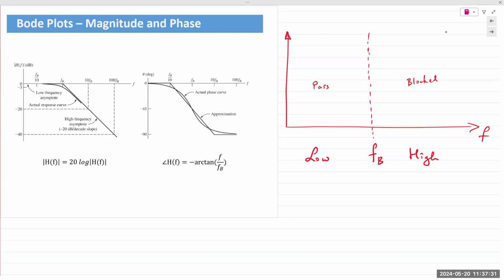So what Bode plots do is you take asymptotes. Asymptotes are straight line approximations to curves, right? In standard geometry, asymptotes are defined as straight line approximations. These straight line approximations allow us to describe the frequency response just by drawing two straight lines. Similar to piecewise linear analysis, you can break it up into individual pieces, and each piece is linear.